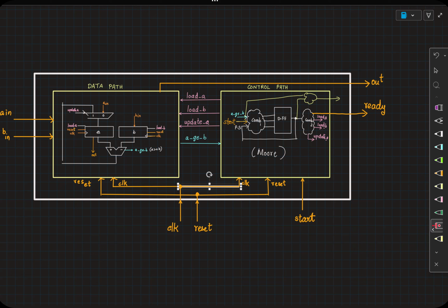So all that he is saying is, if you are representing all your numbers in the registers in 2's complement form, if the number is negative, the MSB is going to be 1. Otherwise it is going to be 0. So if A is greater than or equal to B, your MSB bit is always 0. So instead of doing this computation and then looking for it, you directly take out the MSB bit from the output. Reasonable, a very good suggestion. Okay. Any other questions on this?